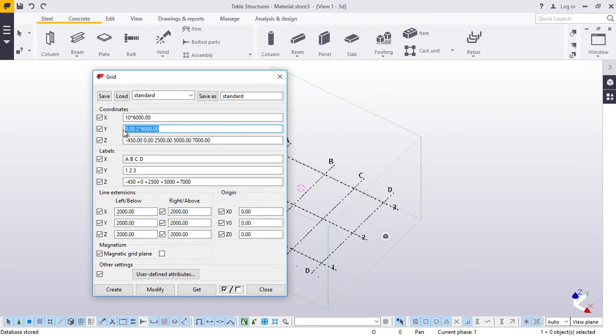we'll feed 3, which actually will have 2 columns, and the mid grid just the midpoint of the whole structure. Now we'll type 3 inclusive the midpoint of the whole structure, and the very important are these 2, 1 and 3. Now we'll type 15 because we need a span of 30 meters. So this will be 15, that will be 15. Perfect. We'll do away with this negative 450. We want all the measurement to start from 0, 0 level.